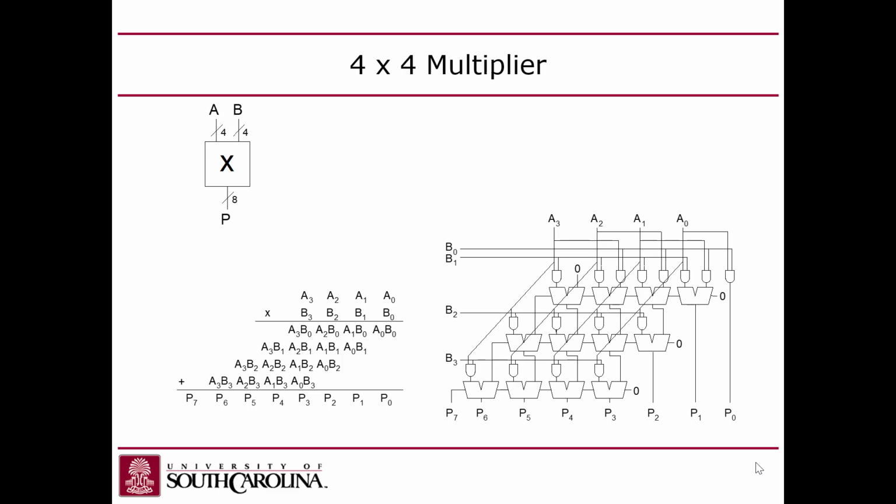So over here we've got A bit 3 that we add to 0. Why do we add that to 0? Well, it's because we still have to bring in the carry out of the previous bit. Now, they could have used a half adder here, because a half adder would have just had A and B and not the carry in, and so they wouldn't have had to put a 0 in here.